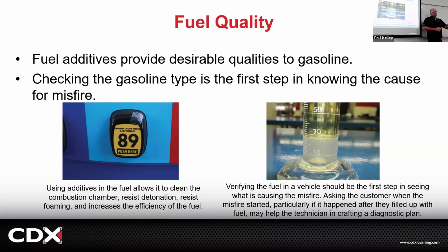So, of course, the fix was get that 5-gallon bucket over here, command the fuel pump on, and I just let the pump empty the tank as much as I could, and then filled it with some fresh fuel, and boom, fired it up. And it didn't run perfect, but it ran pretty good. And I said, burn this whole tank of gas through here, and then by the very next tank, any signs of this watery old ethanol bad gas will be gone. So it wasn't really rocket science, but if you don't know about it, it's kind of hard to figure out.